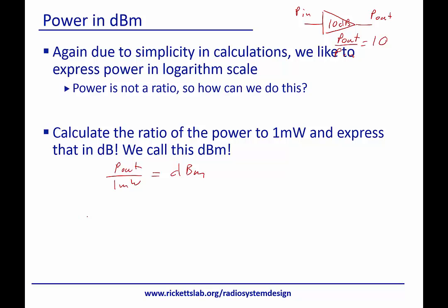As an example, take 998 milliwatts. This would be 10 log base 10 of 998 milliwatts divided by 1 milliwatt.